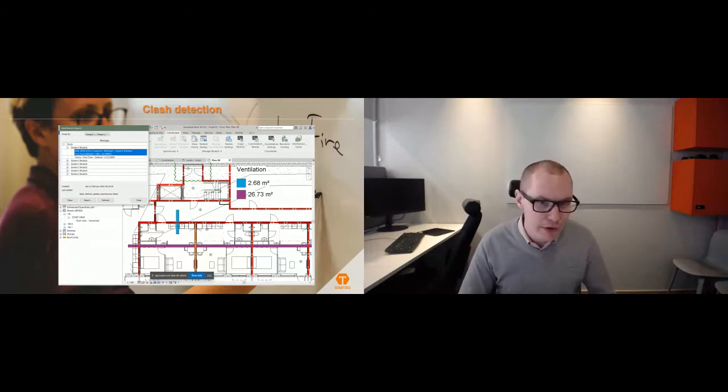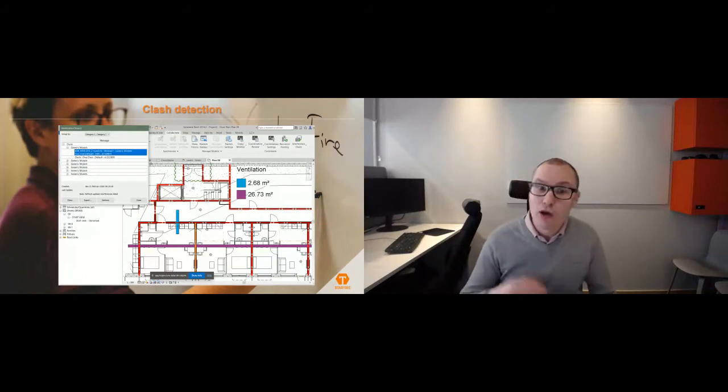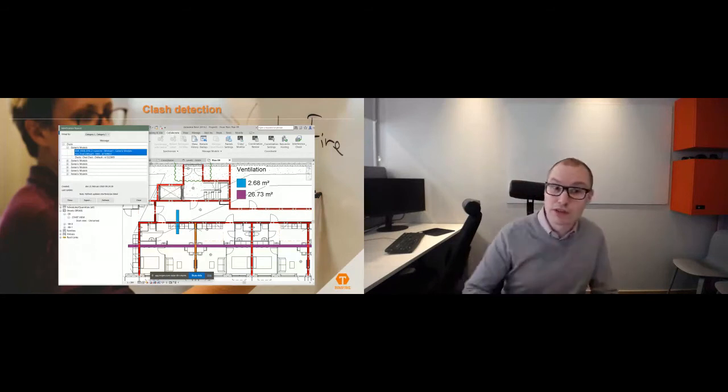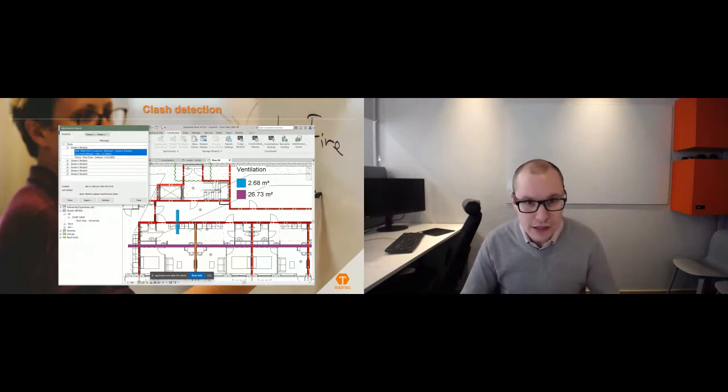Do we have a damper around this? How much fire seal do we need? Could also be if you have pipes, because most pipes are plastic. If you go through a compartmentation, a penetrated compartmentation, you can't really have plastic. You need to change at that part, at least, to a different material that doesn't burn that easily.